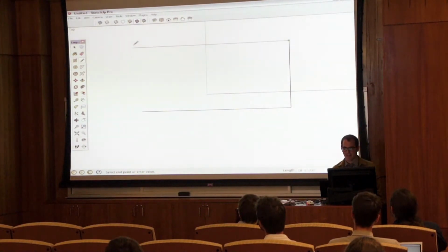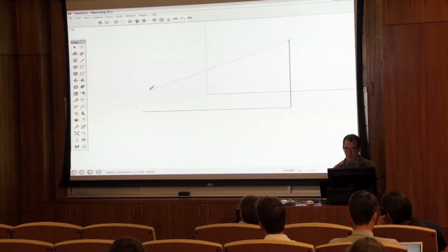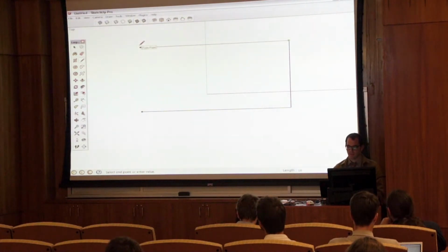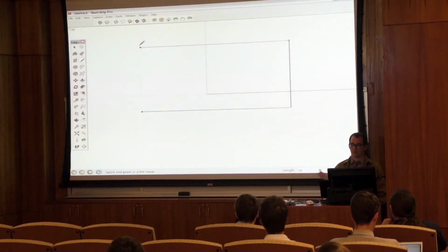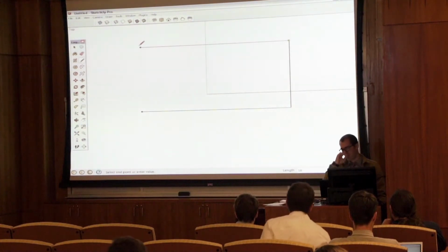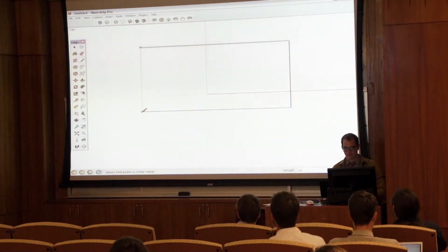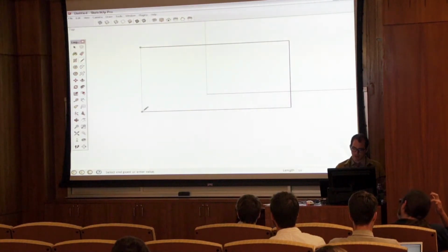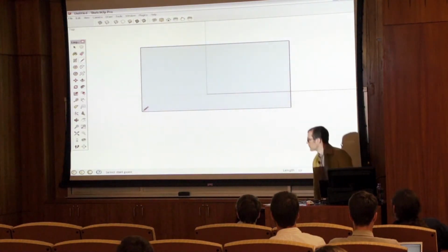All right, for this line here, you could type in, I think it was 17 feet. You could type in that distance, or SketchUp has inferencing. So what I mean by that is you can hover your cursor over this endpoint. See how that little green circle highlights? You can then move your cursor up, and you'll see this dotted green line follow until it actually snaps to that point. So you don't have to retype in that value of 18 feet. You can just simply hover and infer to that point and then draw it.